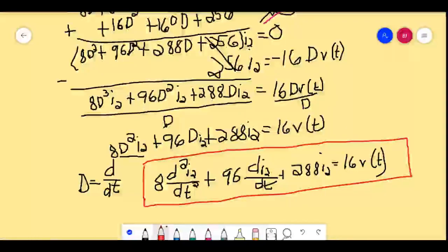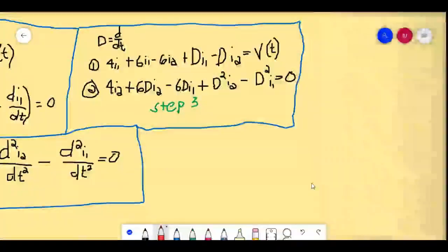So the next step would be involving getting I1 instead. Okay? So we're done with half of it. Let's go to I1 later on. Now, let us apply our fourth step to our second example. So we have to group I1 and their coefficients together for both the first and second equation, as with I2. So for number 1, let me just write here step 4.